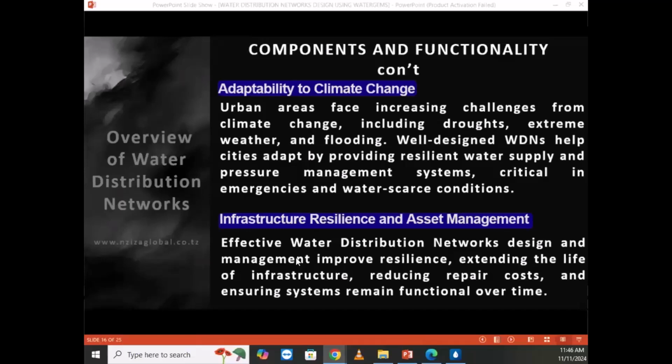When I say infrastructure resilience, let's return again to the case of our manager. If the designer of your treatment plant has designed a plant for 8,000 cubic meters per day, and now you are producing 10,000 cubic meters per day, it means you are not allowing your infrastructure resilience, because your treatment plant will not last as much as it was designed for.